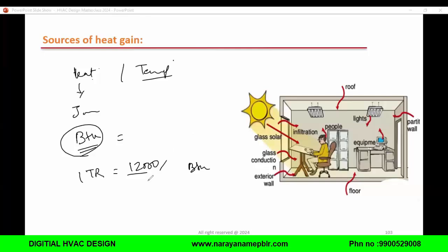Okay, so based on that, for example, if you got 36,000 BTU, you can understand that you require 3 tonnage. Got it? I'm just giving a broad idea, so we'll go step by step.